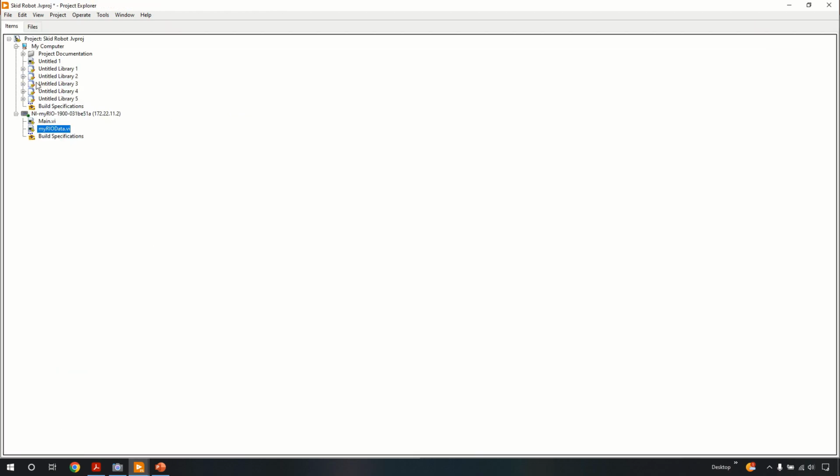Now, if I go back to the tree, I can see that all my shared variables are created underneath libraries. Usually, your shared variables will be stored underneath libraries. And what you need to do is to place them in a single library, at least for this state machine. So I'm going to select them and drop them right there. It seems that I copied this one. That's fine. This is LED2. Okay, I'm going to put 2 here and 3 right there. Perfect. Now there you have it, LED 0, 1, 2.